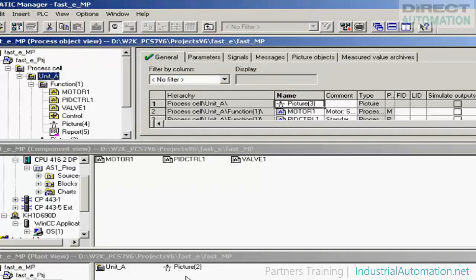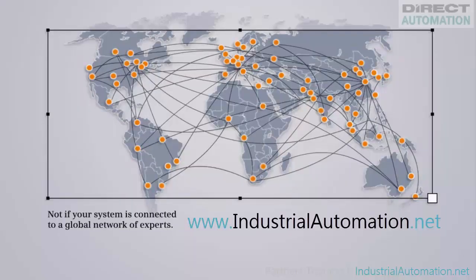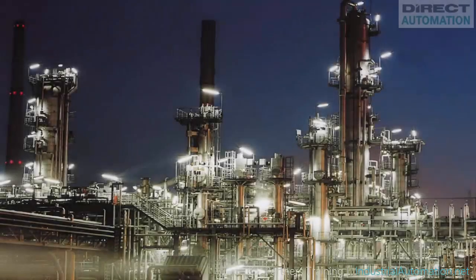The settings are now completed. With these settings, SIMATIC PCS7 will automatically generate all block symbols, create them in the corresponding pictures, and connect them with their associated faceplates when the operator station is compiled.